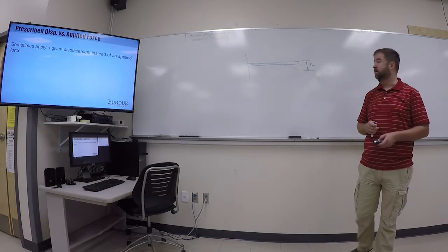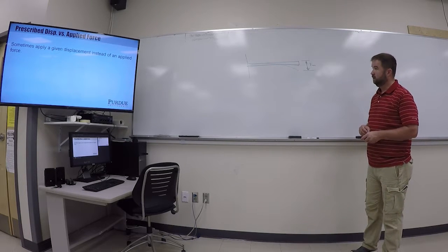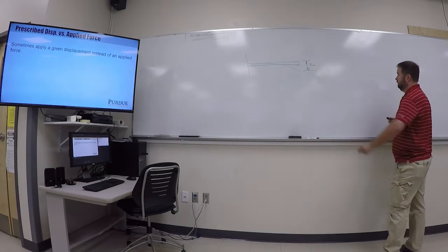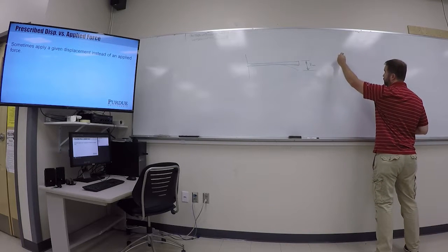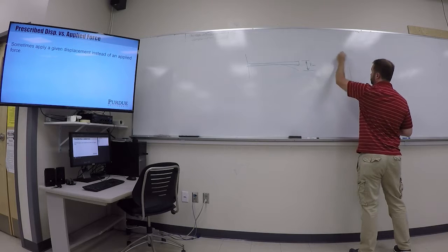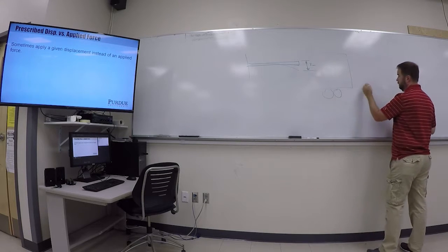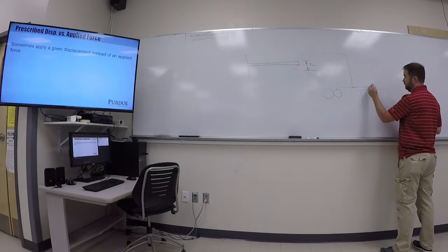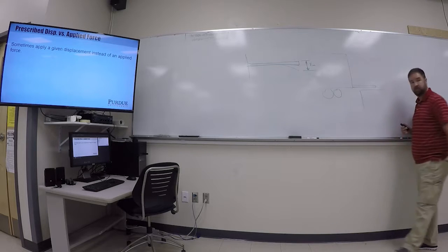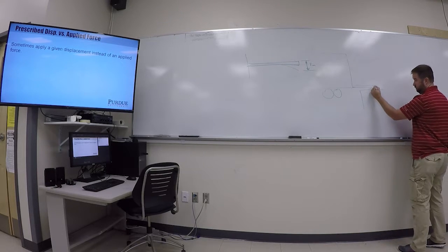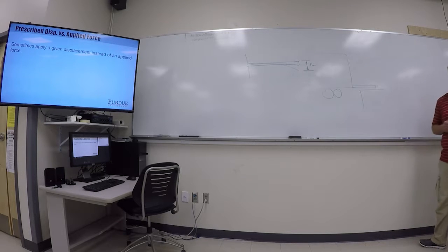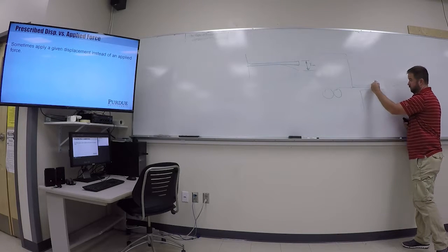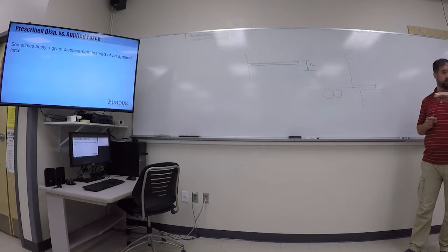So let's say that, I'm trying to think of an example. Let's say that, you know, we're dealing with a loading truck. You've got a truck, and we know that it's gonna back up to a dock, and there's gonna be a ramp on the truck. It's gonna stick out the back, and we know there's gonna be a little bit of gap between the ramp and the dock. And when the fork trucks come and roll onto that ramp, that is going to deflect down as the weight of the fork trucks come on there.